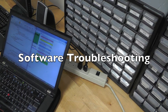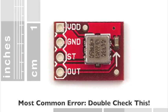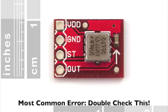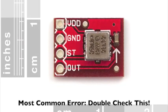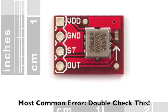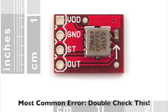When running MATLAB analyses and Arduino supplementary exercises, you may run into a number of software issues. The first thing to check is to verify that parentheses and brackets are properly closed. You may also want to check that proper ports are declared in the Arduino code and that there are no misspellings in your MATLAB functions. If the accelerometer is recording but isn't registering any variation, you should check to make sure that the arrow on the breakout board is pointing in the direction of accelerometer motion. Since the accelerometer is a single axis, it will only measure acceleration in that direction.